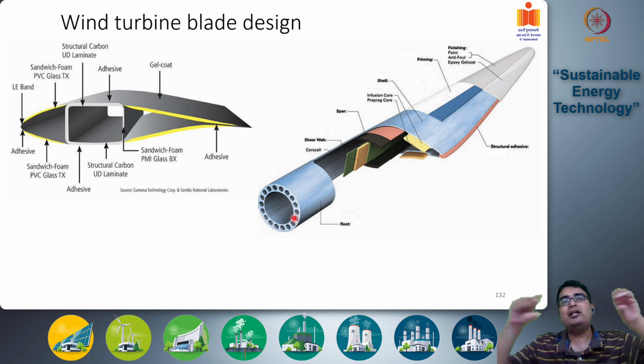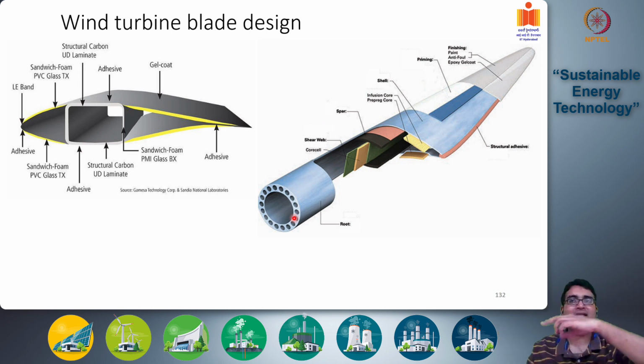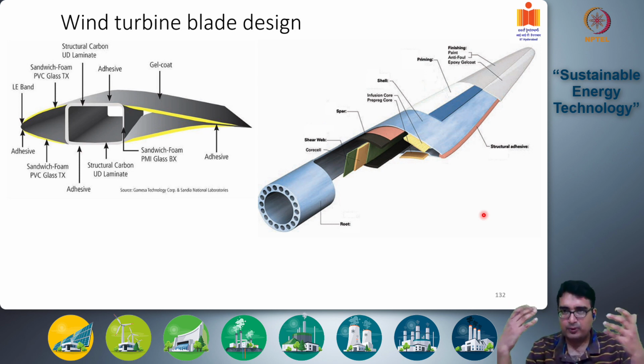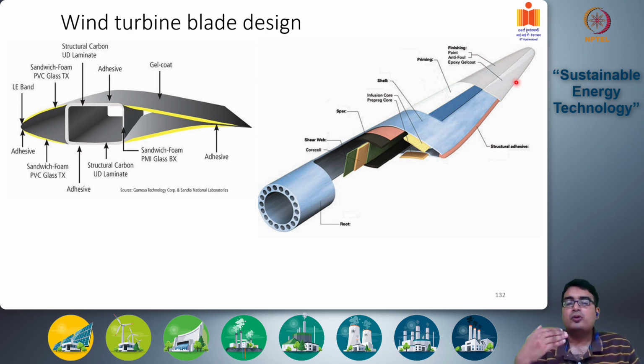Basically a wind blade is like a cantilever. The higher the weight, the greater the stress across the cantilever beam, correct? So this basic idea tells you that the heavier the wind blade, the shorter its diameter has to be, so that the flexural and torsional stresses are lower. Recently, all of the wind turbine blade materials have changed dramatically.